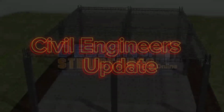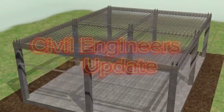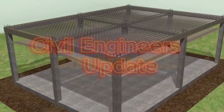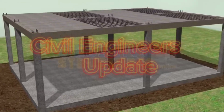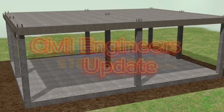Slab shuttering. Beam bottom is first laid on the column and then slab shuttering is laid. Beam and slab levels should be maintained as per drawing. Slab concreting. After the concreting of column, beam and slab concreting shall start monolithically. The top of floor beam and slab shall be maintained as per levels.